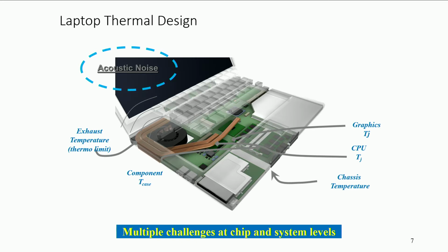So during testing here, I will put a thermocouple on top and make sure that the temperature is below 85, or even in the model I will put a monitor point on the case. The assumption is that if the temperature of the case is less than 85, the junction is also within its allowable limit. All right. So non-CPU components, what else?